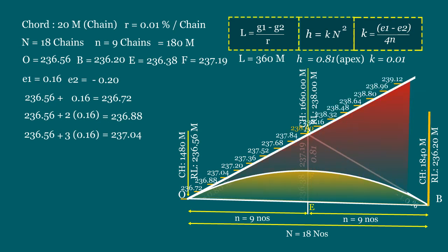That is, the extended tangent of grade 1 until point C. Finally, the elevation value of 18th peg is RL value of 0.0 plus 18 times the value of E1. That equals 239.44.